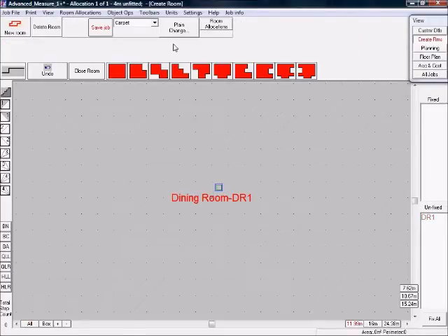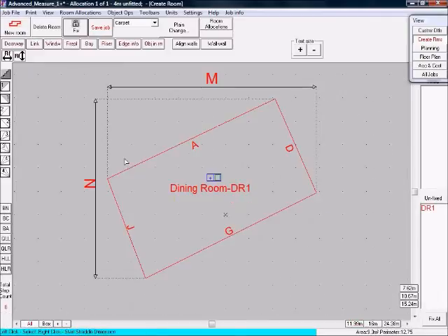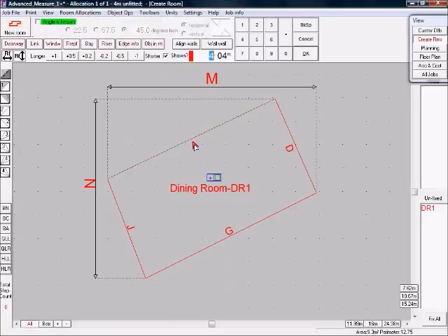Click on wall A and say that the angle is known. The bright green guides you to do this. The angle is currently stated at 45 degrees. We actually want it to be at 22.5 degrees, so click on the radio button that gives 22.5 degrees and say that this angle should be to the horizontal wall. Now enter the length of the wall to be 4.5 meters. You will see that the shape changes to accommodate this length and angle. Now we need to enter the angle and length of wall D.